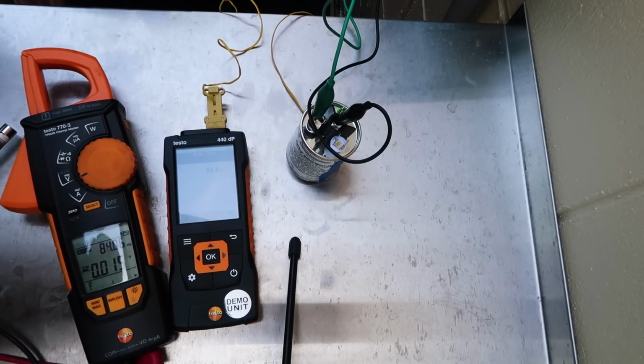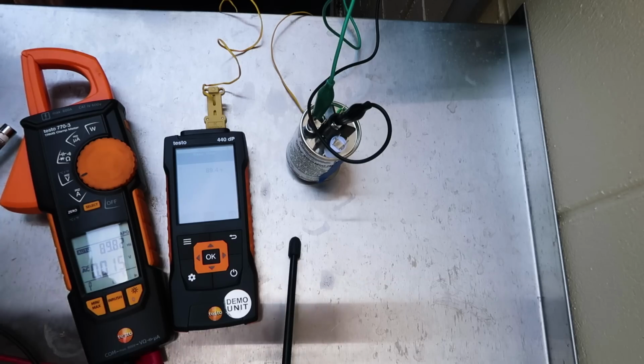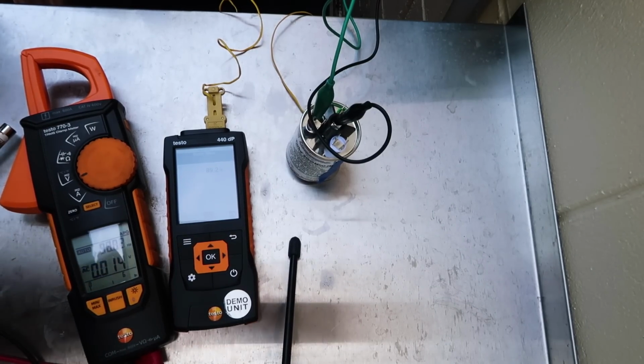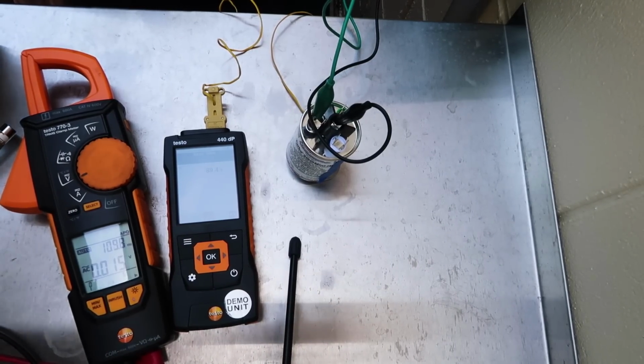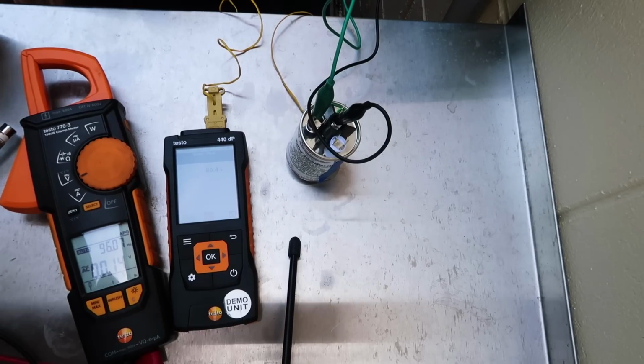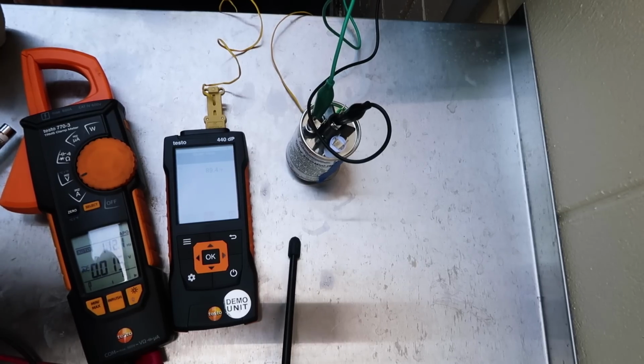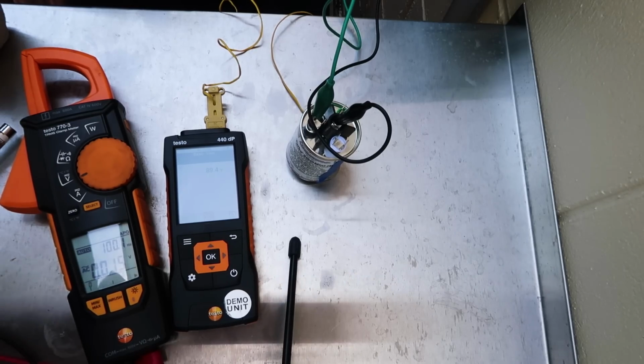That's not going to change what it does other than the voltage, the back EMF being applied from the motor. So if you measure that applied voltage across those terminals and you know the capacitance of the capacitor, then you're going to essentially know the amperage. You know what it's going to be. If you think about the capacitor equation that we use for calculating capacitance, you take the amperage of the start winding, you multiply it by 2652, and then you divide it by the voltage, and it gives you the capacitance of that capacitor. It's in a 60 hertz application.